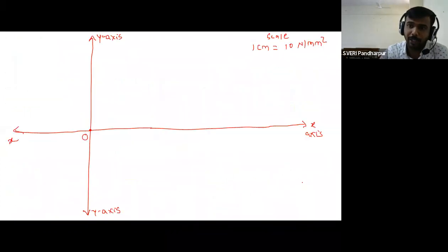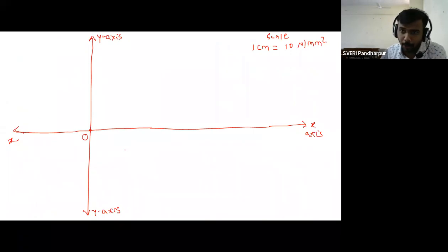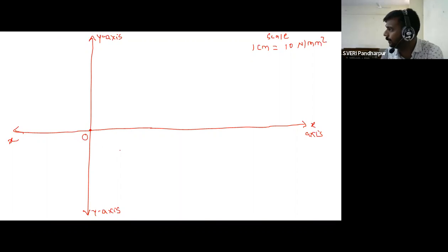You have to write down the scale also on this particular figure. Okay, now see, we have to represent sigma x and sigma y on the horizontal axis only. Correct? And we know the dimensions. Sigma x is equal to how much? 100 Newton per mm square. But as per the scale, it is equal to...